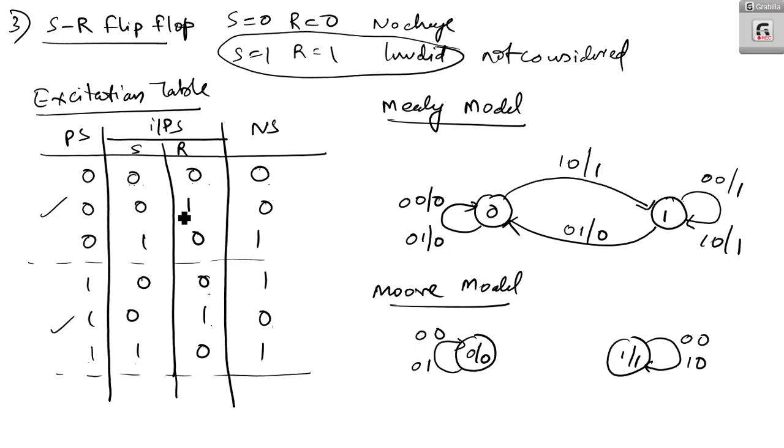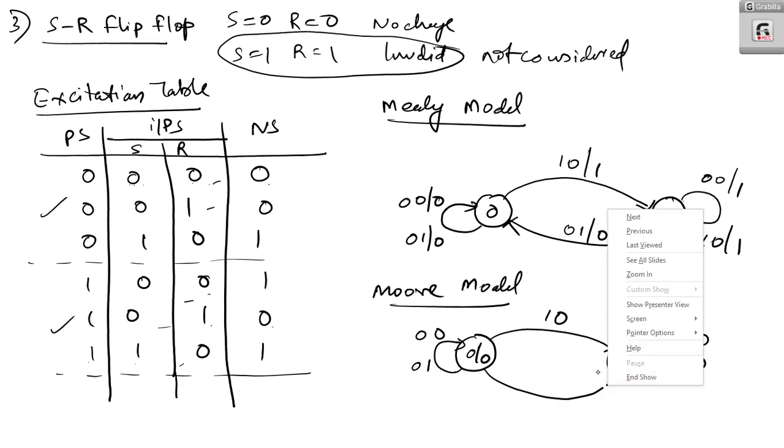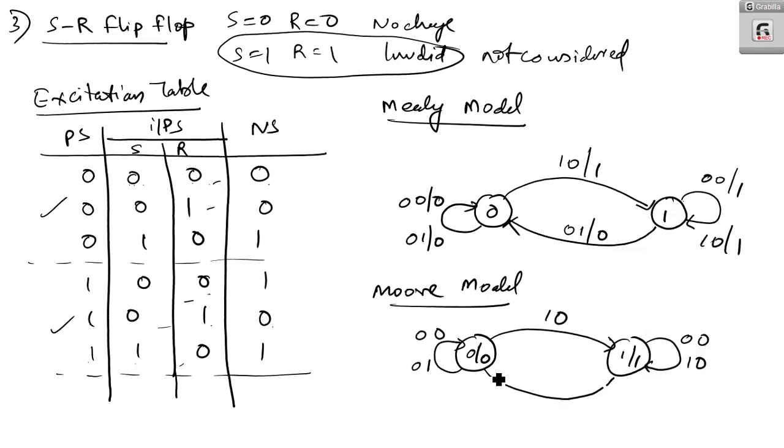Now, coming into 0, 0 and 0, 1 is over. Now, coming into 1, 0, it will go to next state, that is 1. So here you will get 1, 0. Then here 0, 0 and 1, 0 is over. So with 0, 1 it will go back. Okay. So that is the basic Moore model. Hope you have got the difference between Mealy model and Moore model.